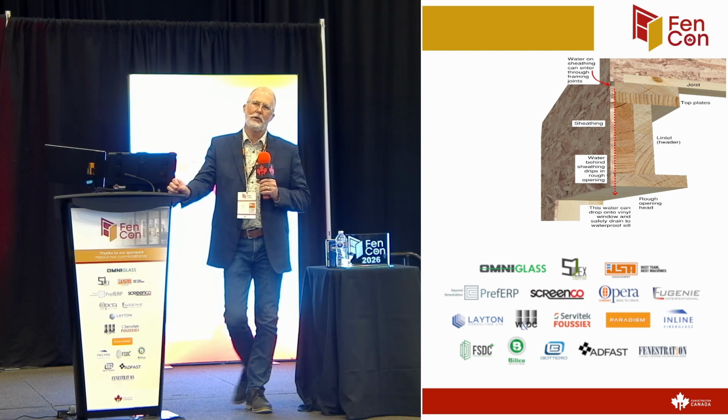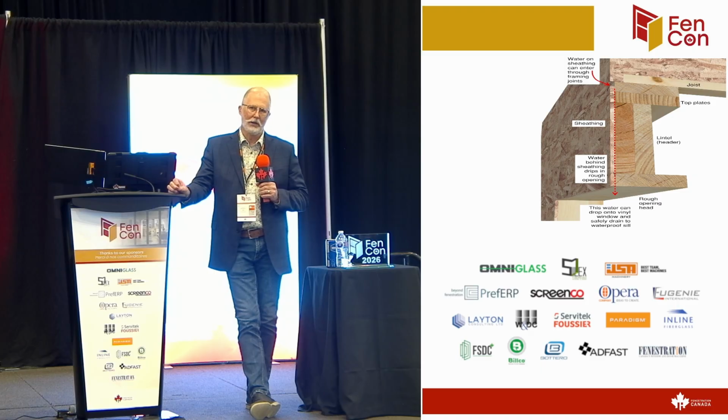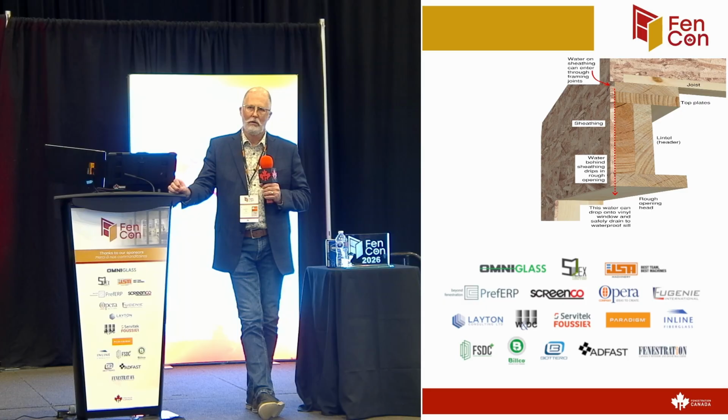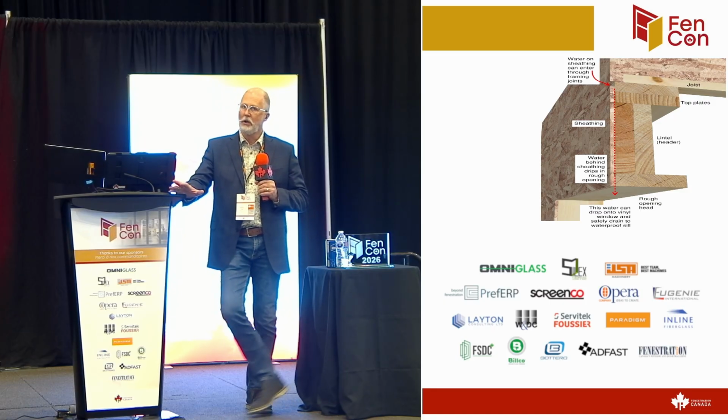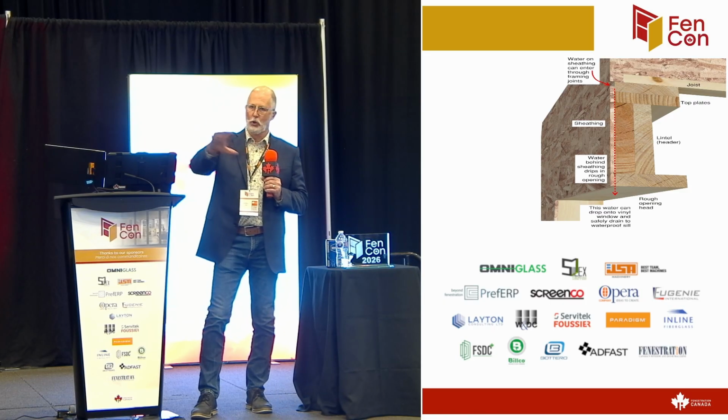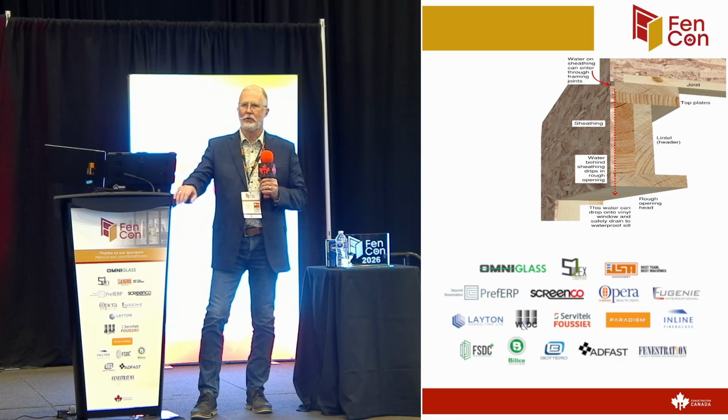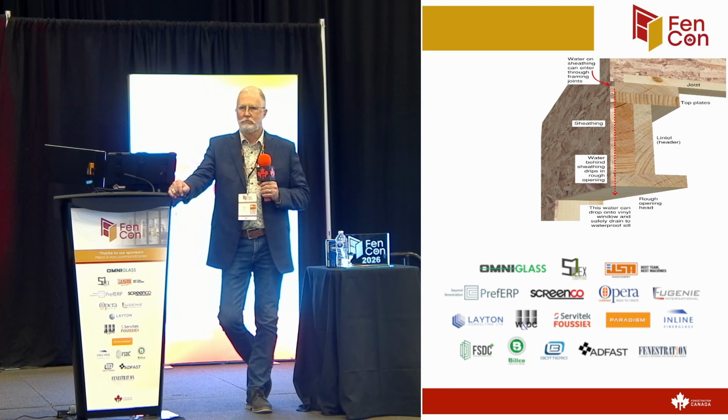Right. So how do you explain a curtain wall working then? So yeah, you still have air and moisture getting to the air and vapor barrier plenum past the insulation, and that becomes your curtain wall principle. That's your plenum. I think that's what we're trying to do with the windows, is take that principle of pressure moderation and just reduce the flow. And if we reduce the flow and water gets in there, we're kicking it back out. That's all we're doing.